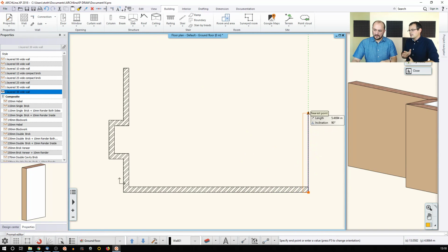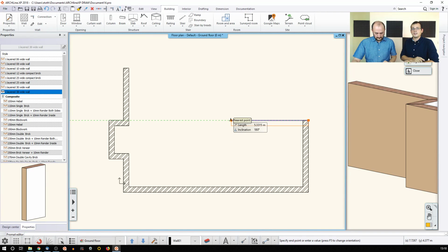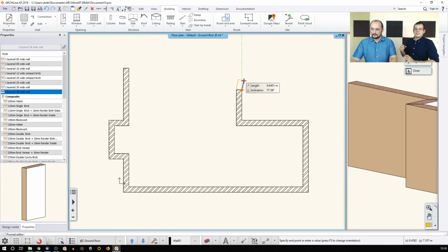Now, one thing that you mentioned is that you're working in meters, obviously you can change that later on, and there's one other very important thing. You don't need to just add the values as they are. You can add up tinier parts of the same values. So if you don't know the exact measurements and you have a survey plan like this in front of me, you can just type in the numbers with a plus sign. You can add factors and you can add modifiers to add the value.